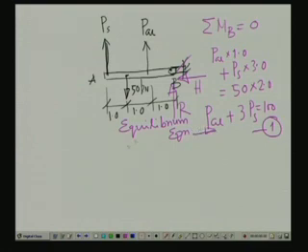We are not looking into the other equations, which are summation of vertical forces equal to 0 and summation of horizontal forces equal to 0, from which we will get R and H. We have 4 unknown forces, Ps, P aluminum, R and H, and we have 3 equations: summation of horizontal forces 0, summation of vertical forces 0, and summation of moments at this point equal to 0.